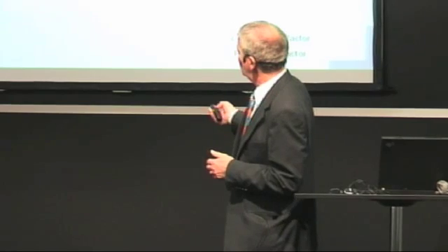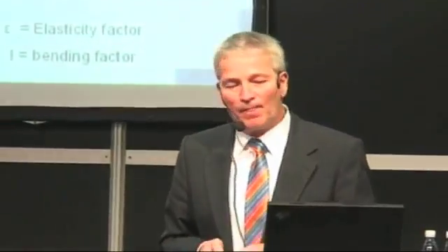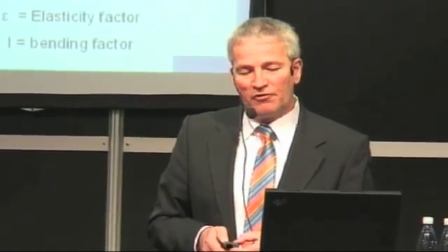It's very similar to this component that you can see here. You have a certain tool diameter, you have a certain tool length, and when you look at a drill, it looks very similar. The challenge here will be the tool overhang and deflection. It's not a guided tool. We have just two inserts on the front, and there are some forces acting on such a drill, a force acting here on the front.